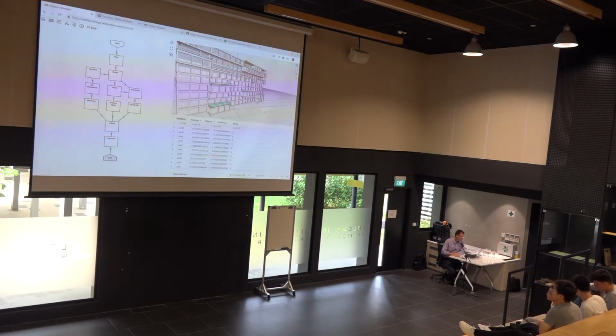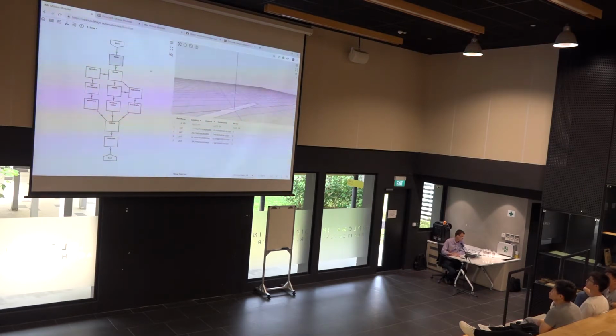The parametric way of thinking is that you structure it as a skeleton first. So you try and create a model where you start with a very simple skeleton of the whole thing, and then you add information. So we start with the base, which is just the base of the model. So the first node creates the base, and the second node creates a bunch of floors.